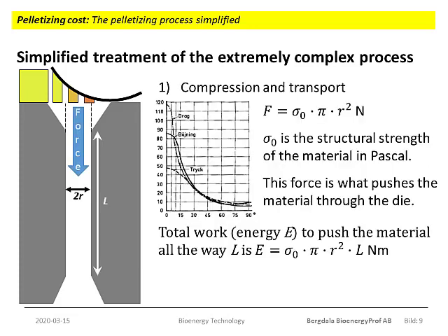So what happens is that we have to apply a force to give a pressure exceeding 50 megapascals. In most practical situations a slightly higher pressure is applied, and as a normal value 700 bar is often mentioned. So that is 70 megapascal. But let us use 50 for our estimates.